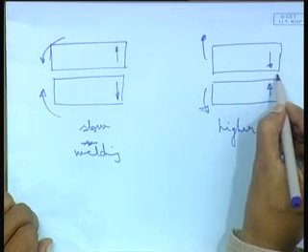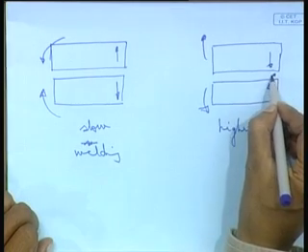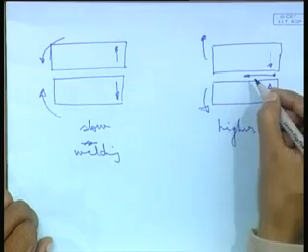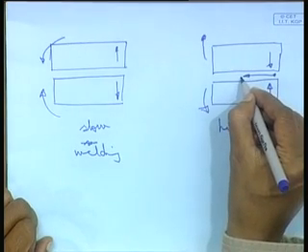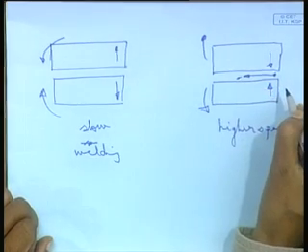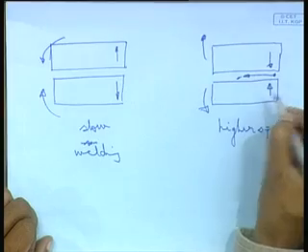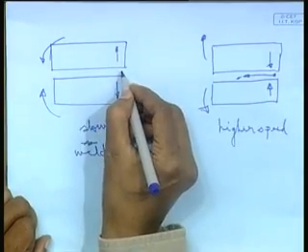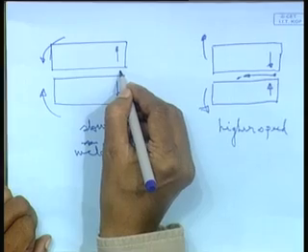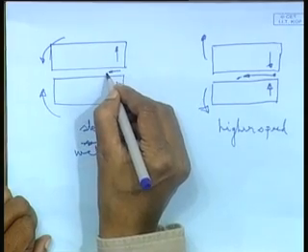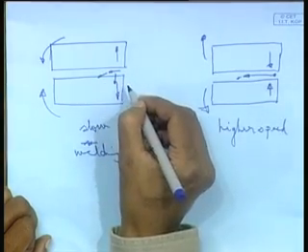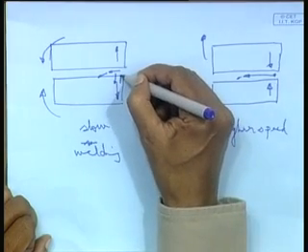So, basically what is happening in higher speed welding is it is going very fast, which means the heat flow in the forward direction is absolutely nominal. Before any heat can flow, it is going faster. Whereas in this case, it is going very slow, heat flow is substantial in the forward as well as in the side direction. So, the shrinkage forces are more.